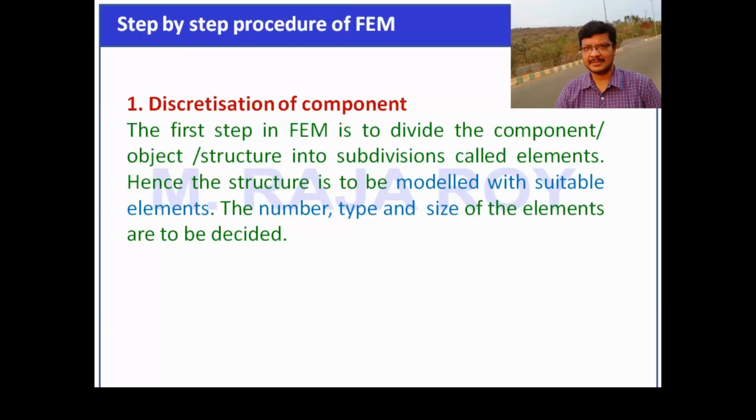Step-by-step procedure of finite element method. Discretization of component. The first step in FEM is to divide the component/object/structure into subdivisions called elements. Hence the structure is to be modeled with suitable elements. The number, type, and size of the elements are to be decided.